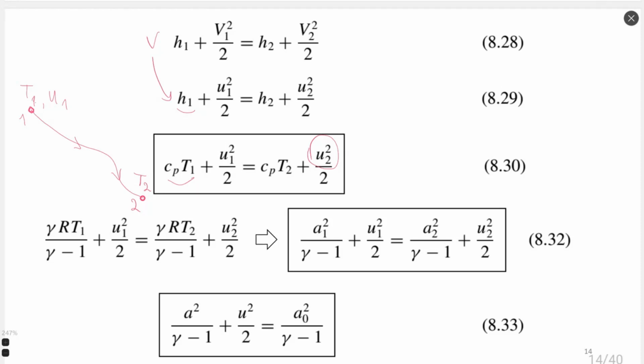When we can calculate some flow properties, just measuring some other flow properties and obtaining more complex parameters that could not be measured directly. Right. This is valid for compressible flows. All flows are compressible in real life, probably you already know, but some flows are less compressible. So equation 30 is better to apply in highly compressible flows when we can determine change of temperature because of